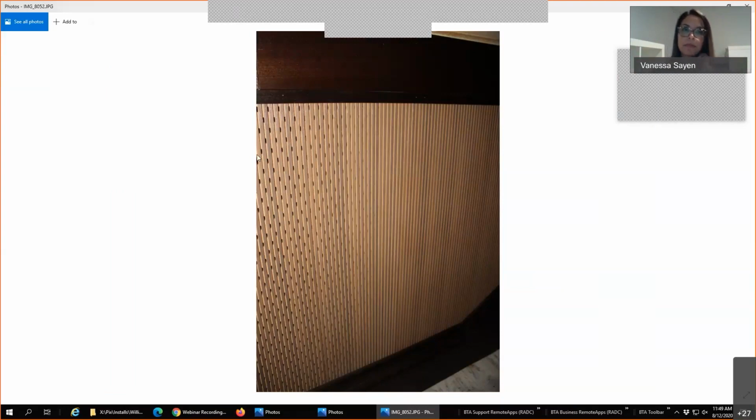Okay, so we have two techniques. In this particular one, this client's room was a reference room. This is big boy stuff. So he has his own air conditioner for this one room with its own thermostat on off. The air conditioner was up in the attic far away. We did an inline muffler so that the air return and supplies were quieted down, right? So that's one way of doing it. Like in my house, I shared an air conditioner, but I had a dedicated run, so that goes right up into the air handler, so it's fine.